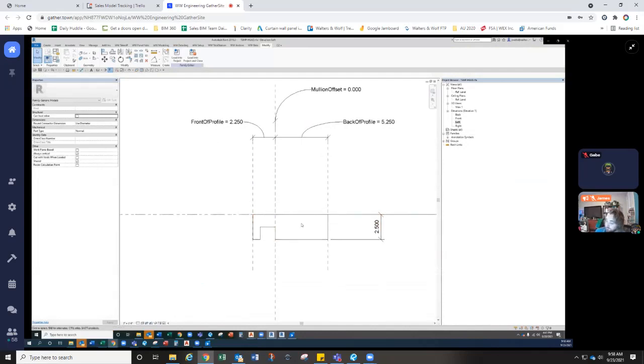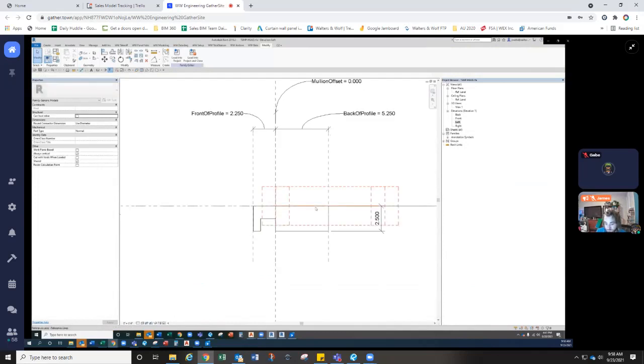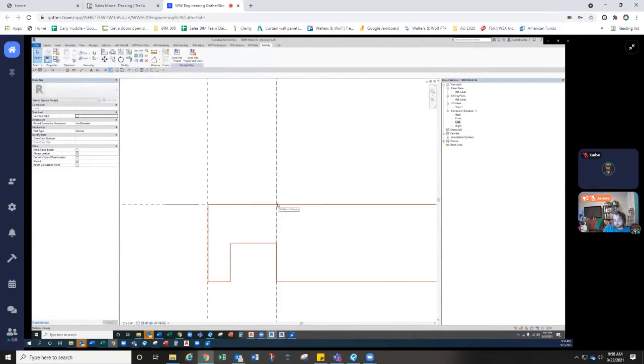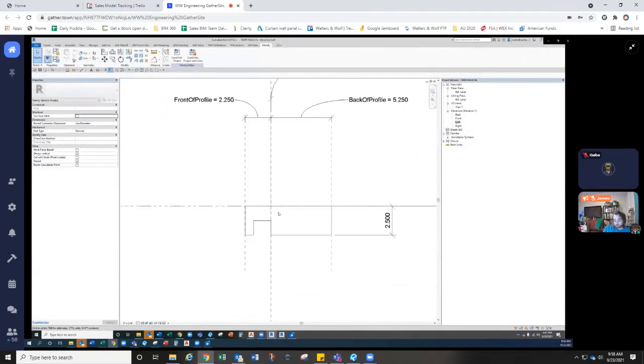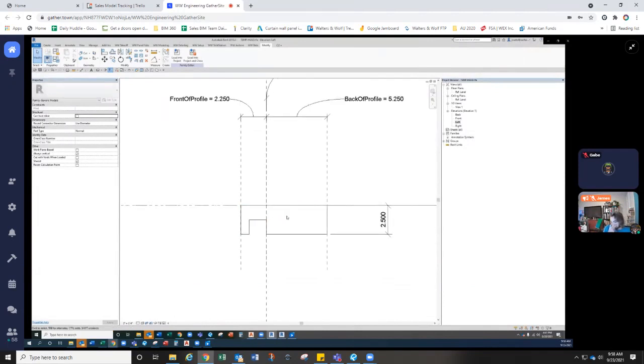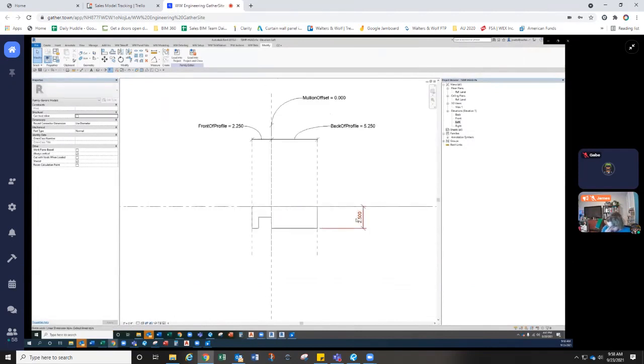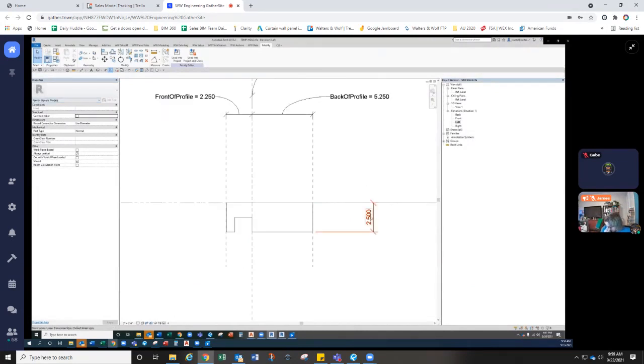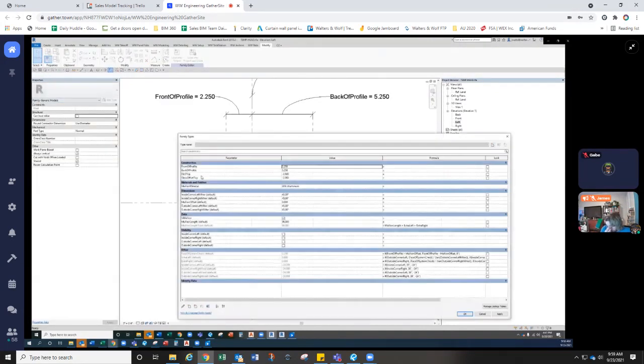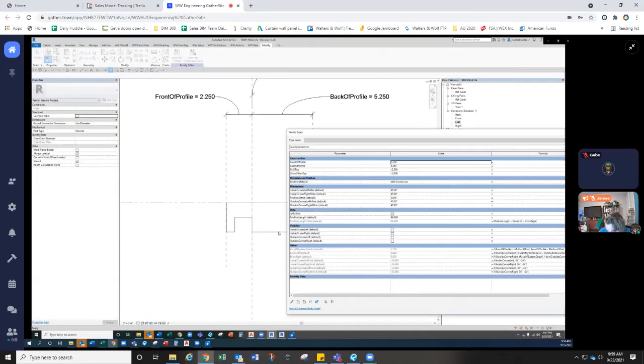So when we make these units, the back pans and shadow boxes are going to come up to this center point, because that's the datum point we're picking from AutoCAD to load in our mullions. Then Alan's tool is able to read the DLO top and set our back pans and shadow boxes to be -2.5 from this point, which was set at the very bottom of the mullion.